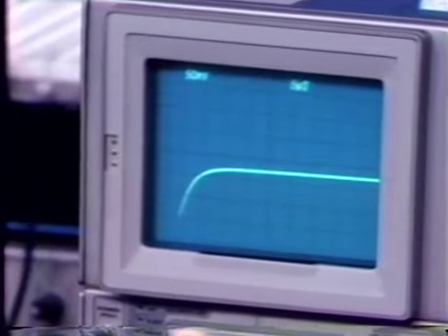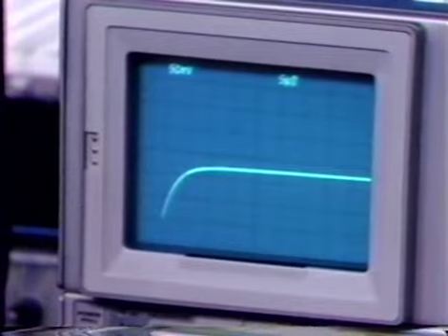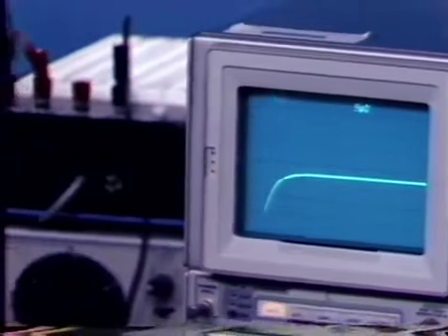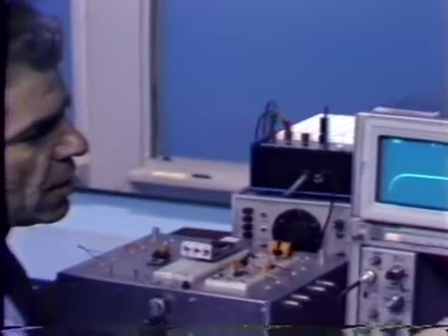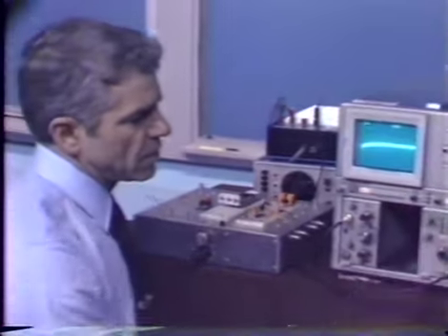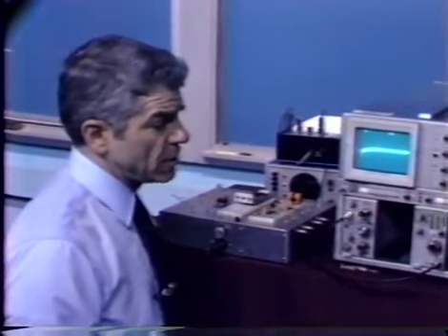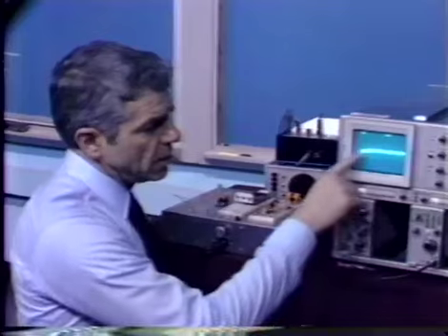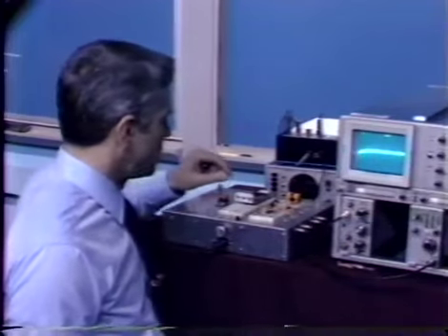Well, what we find is, again, a delayed settling time. This sort of compensation again gives us a pole zero doublet if we look at it. We get to about 90% of final value very quickly on the leading edge, but it takes much, much longer. The response is basically two exponentials, one of which has a much longer time constant than the other one, and we see the quite prolonged settling to final value.